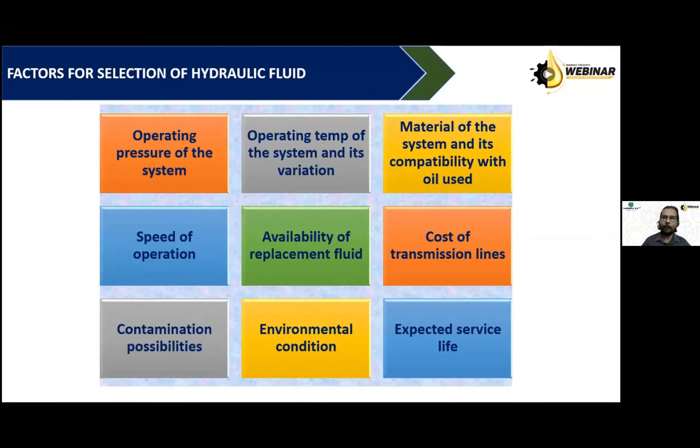Factors for selection of hydraulic fluid we have discussed in the previous slide, and we try to summarize it here. Like operating pressure of the system. Operating pressure of the system is again related with demulsibility of the oil, and capability of oil to handle the foam. So we should have sufficient anti-foaming agent or defoaming components.